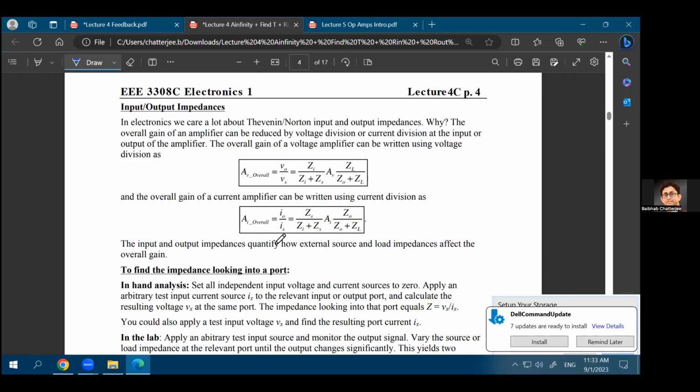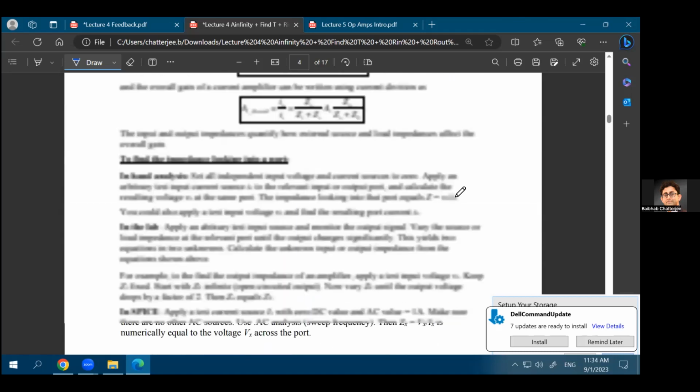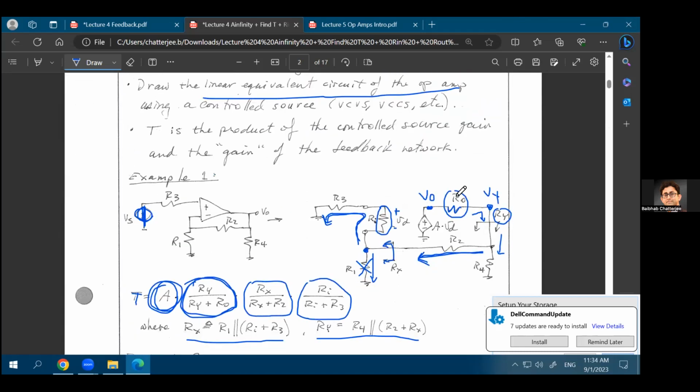But how do you know where to put RX, and how do you know that RX is R1 and so on? Oh, the choice of RX is arbitrary. Why are you saying that this point is RX? Like, why do RX and RY exist? They do not exist. It's something that helps you to do the calculation. What exists is just R0, R4, R2, R1. These are physical resistors. So you're saying RY here is R2. RY is R4 in parallel with R2 plus RX.